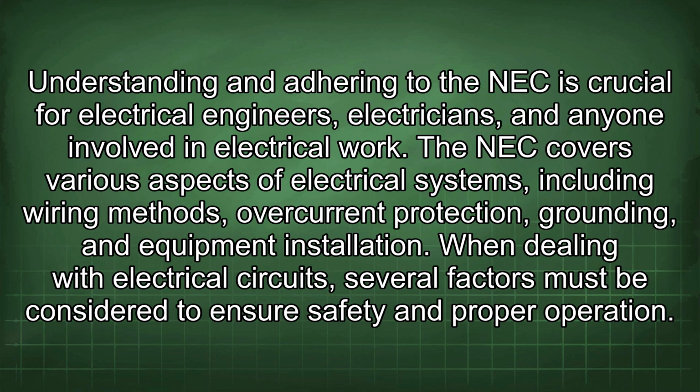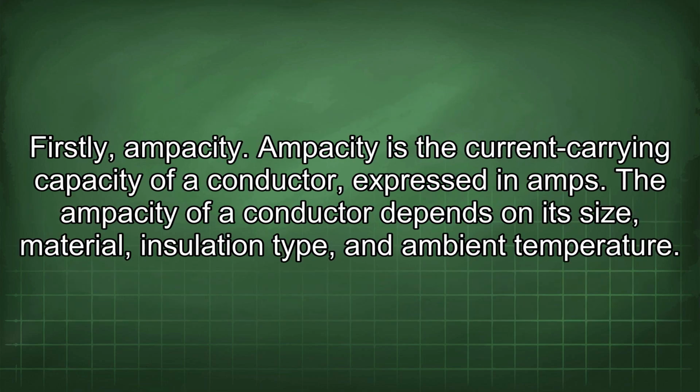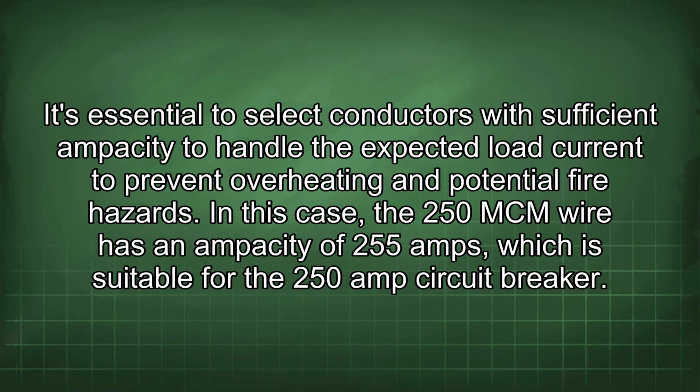When dealing with electrical circuits, several factors must be considered to ensure safety and proper operation. Firstly, ampacity. Ampacity is the current carrying capacity of a conductor expressed in amps. The ampacity of a conductor depends on its size, material, insulation type, and ambient temperature. It's essential to select conductors with sufficient ampacity to handle the expected load current to prevent overheating and potential fire